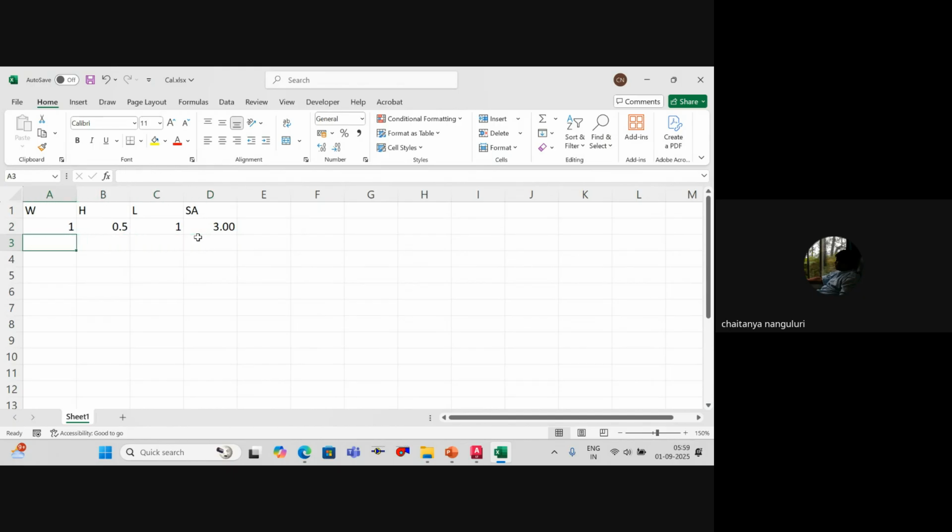So this one is done, and now let's do the second one. The second option is, let's say, 2 meters, 0.25, 1 meter. Now, if you do this, don't you think your area is 4.5? So don't you think you will consume more duct material or not? Yes. So you have 1.5 square meters which you're wasting, ducting material which doesn't have any use.